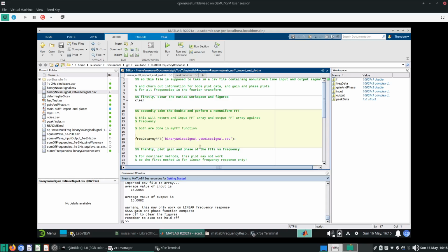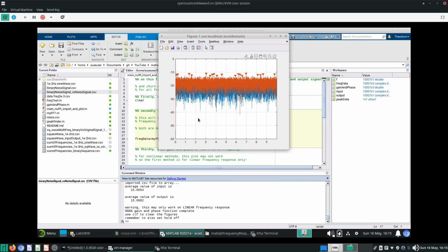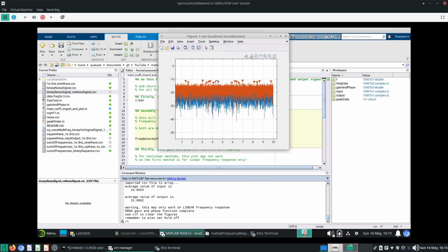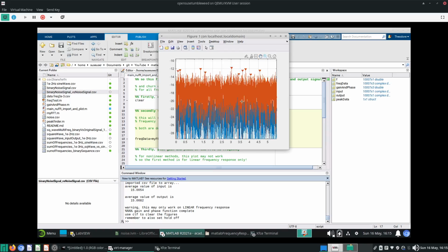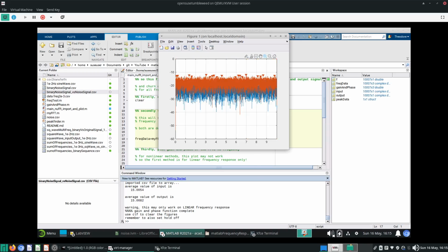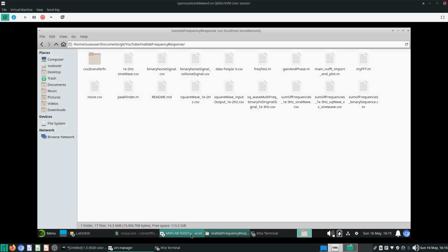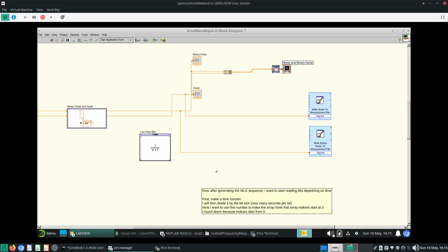So if you take a look at this MATLAB, and you say, I don't want to deal with the higher frequencies, I only need to deal with the lower frequencies, I can insert a low pass filter, and most of the higher frequencies will be filtered out. That means you won't see them in this Fourier transform diagram. So we'll try the low pass filter. I will try to write it for a while, and we'll see what happens.